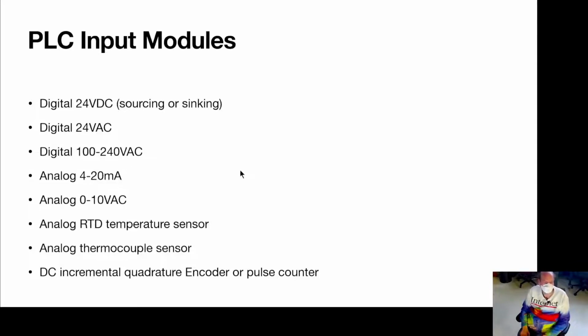We have a question? Yes, we do. From the interwebs: do the AC inputs require AC, or do they respond to an RMS value? The way they're implemented is the same as the DC inputs, with an optocoupler inside. So there's a little light on each input physically inside of the PLC. If you reach the voltage it's looking for, it will light up and then signal that down inside of the PLC. So a 24 volts AC input might not turn on at 24 volts DC, but there's a voltage it will.